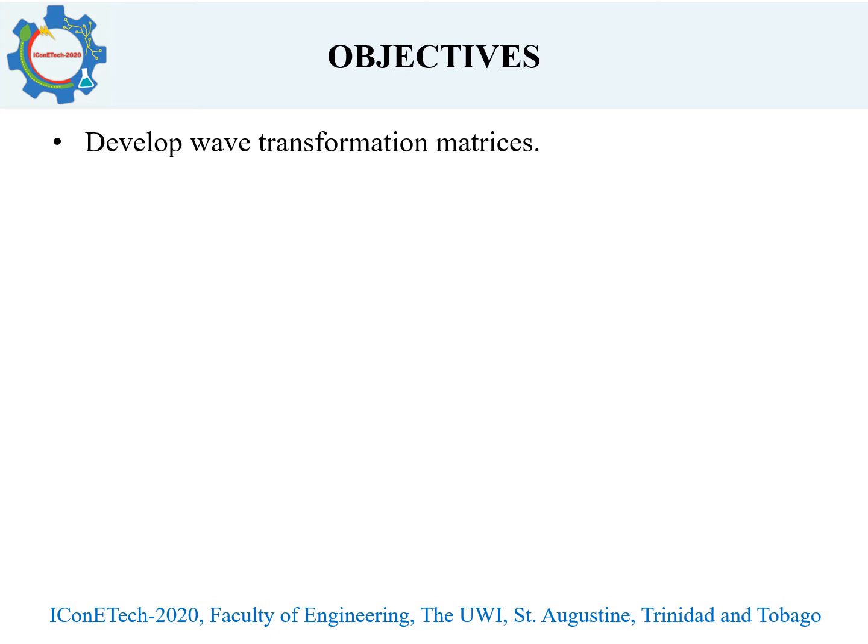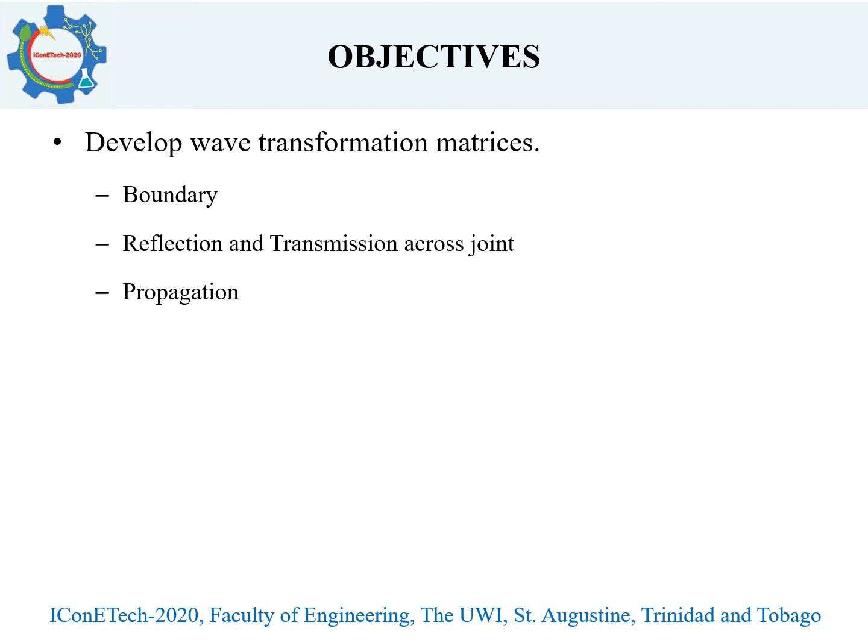So in order to properly model the response of the L-beam structure, first the transformation matrices must be determined using the fundamental equations. These include the boundary matrices, such as free, fixed, or simply supported edges, reflection and transmission across the joint, which I'll go into later, and the propagation of the waves along the beam elements.